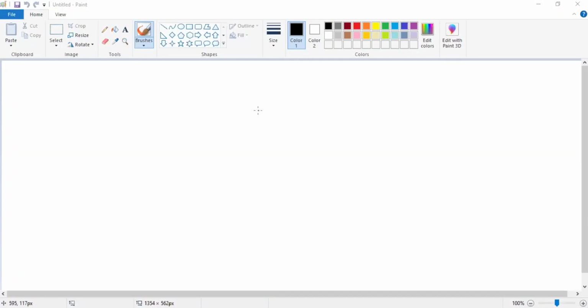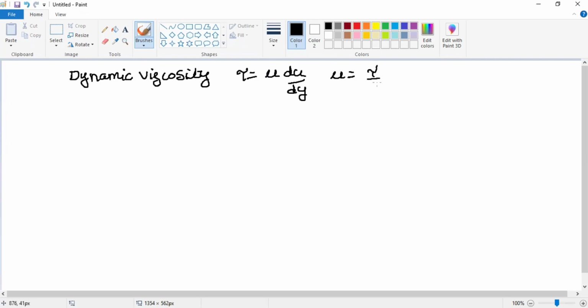Hi, Namaste. In the previous video, we discussed dynamic viscosity. That is tau equal to mu into du by dy. From this, mu equal to tau by du by dy. We know the units are Newton second per meter square.